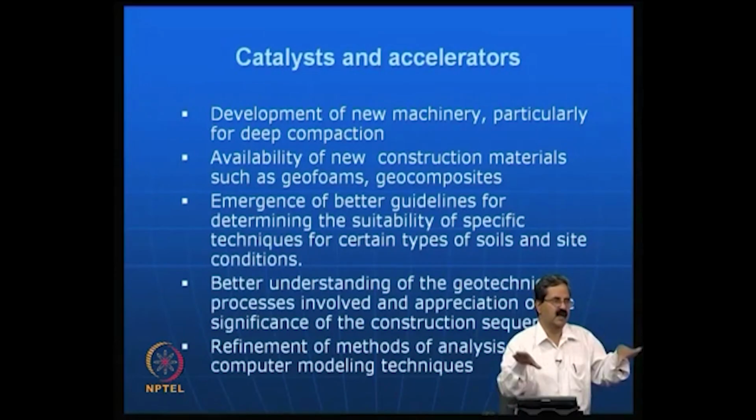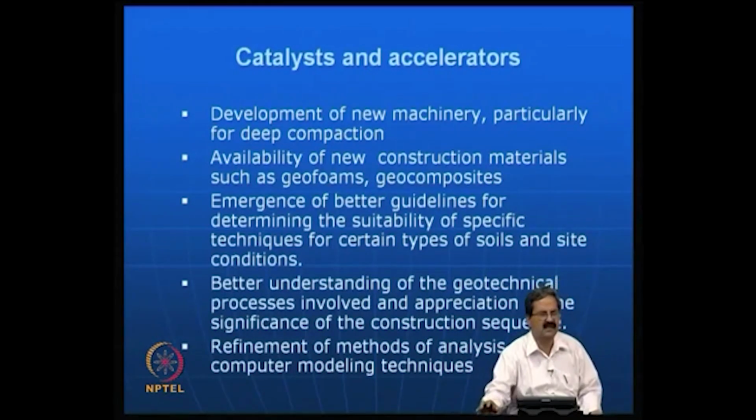See what happens if you put soil and start compacting, actually our people will not compact at all, people will be simply slipping there. But here you can use soil plus fly ash, make a mix and then pour that, and then the setting time will be about 4 hours. Once it is set, the road is ready, it can be used. I have seen some field examples where these sorts of connections are made in no time.